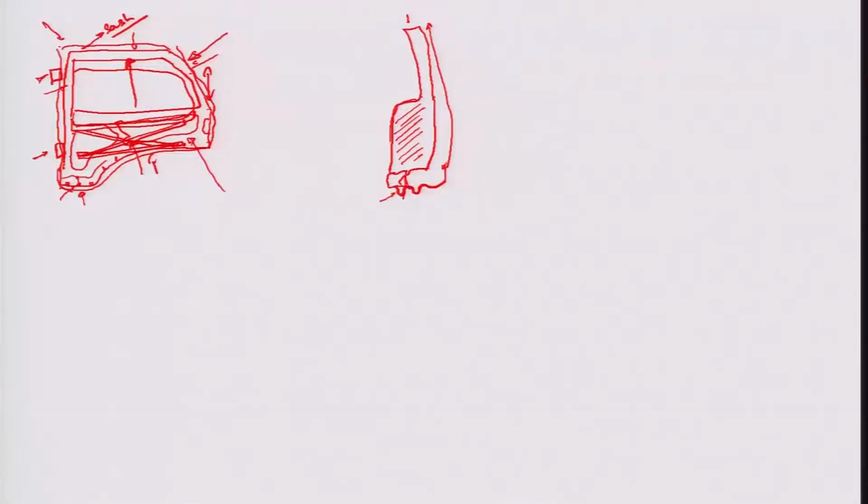So just before the final paint coating and the end of the ED process, on the line there is a wax applicator which would create a sort of wax layer on the door inside, meaning we are targeting this particular region with a wax layer, which we ooze out through a wax gun on the line. Typically in a paint shop, this process may look like trolleys carrying the automotives with doors in open position and the wax applicator with a manual